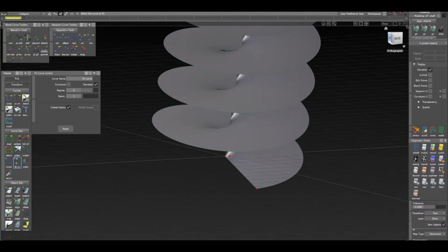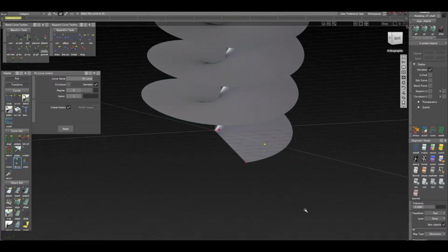Okay, and what we're literally going to do is create at least one section of spring or tube, and after I show you how to make one section of a curve of a tube, you'll be able to make subsequent sections on your own. Bear in mind, this is a very labor-intensive process, and the tubular offset tool is going to solve like 90% of your problems. So this is kind of academic, but it's still important to know. It's still good to know. So we have a rail surface here, and I'm just going to zoom in.